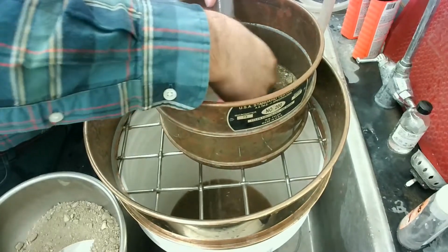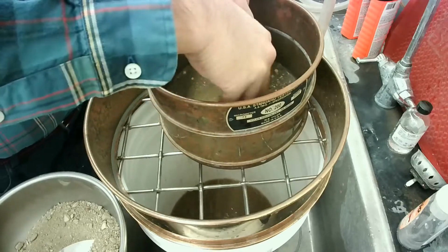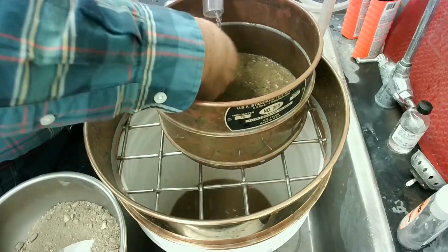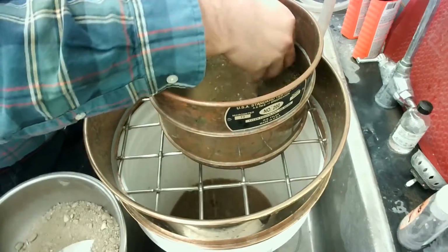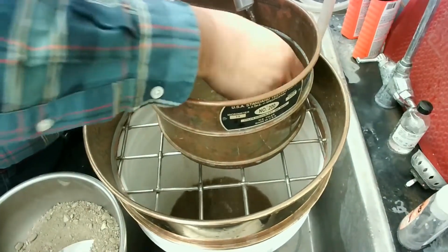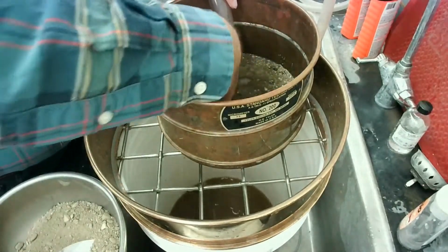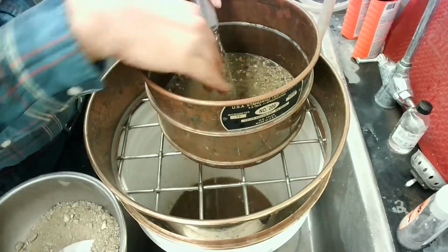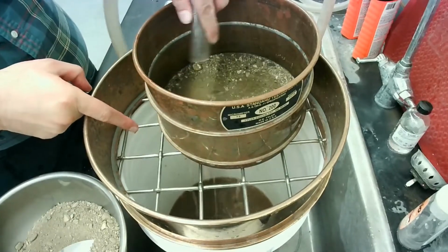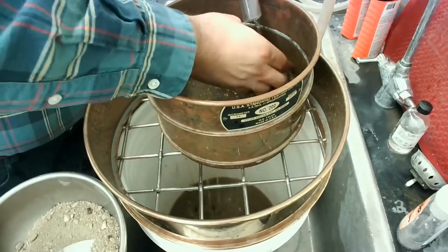So I want to give this kind of motion to my hands to make sure that the water goes through all the solid particles here and that all the fines basically get washed. I want to make sure that I collect most, if not all, of the fines that are in this soil. Right? And the result would be that as I get all of the fines out, the water underneath is starting to clear up one more time. So same process until I get all the fines out.